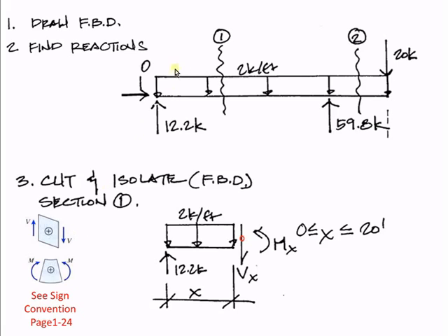If you treat the loading diagram and create a formula with that sign convention, you can simply integrate to determine the change in your shear diagram. The formula for the loading diagram, integrated, will have a consistent sign convention with this type of positive shear and this type of positive bending moment.